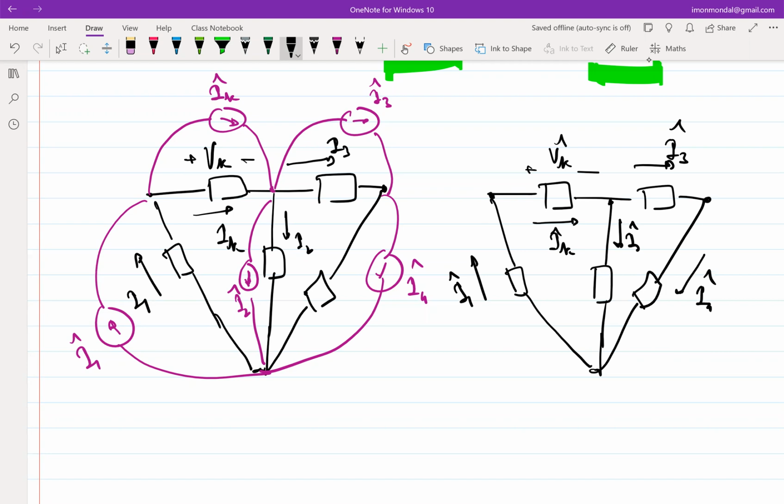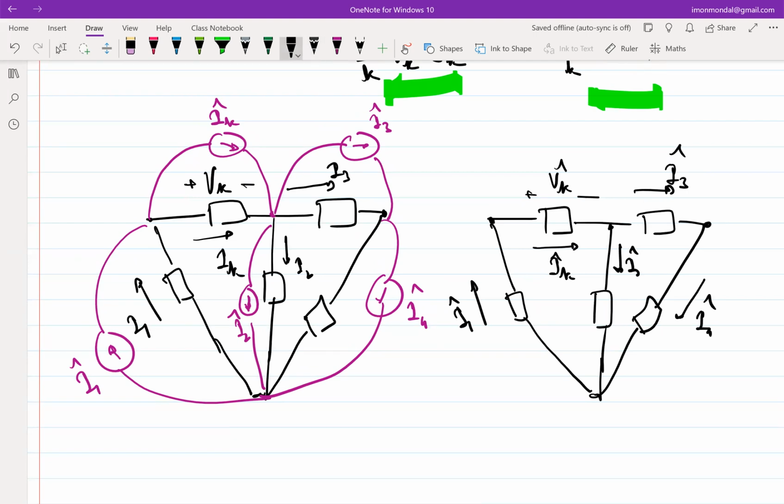Okay. So note why am I saying that doing this will be adding zero current: if I look at this node, what is this node telling you? It's essentially telling you I1 hat equal to Ik hat, if the direction is the other way around. And this node is telling you that Ik hat equals I1 hat plus I2 hat. So essentially, the KCL at each node on the circuit on the right satisfies that current going in is equal to 0. I have just superimposed that same KCL condition on the circuit on the left by adding up the currents in the direction it was in the circuit on the right.